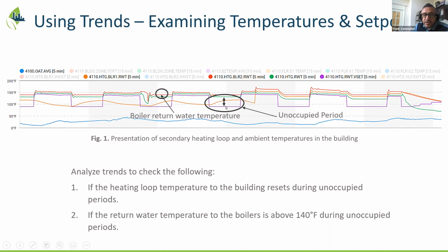Well, if all the individual convectors or their valves are opening up because you're trying to cool off the building, 130 degrees still gives off quite a bit of heat. So we were trying to figure out why that isn't happening, and that could be a big contributor to a loss of savings, for instance.